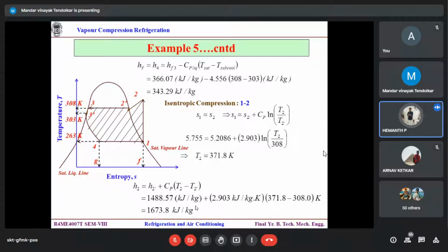Sir, while subcooling, the process will be a constant pressure process, right? Constant pressure process, yes. Because we have already stopped at 3, which is already saturated liquid, and then we are subcooling. So we will be exiting the dome, right? Yes. So I thought you have drawn it on the... Here. So we have exited the dome, right? Yes. Okay. It is slightly outside, left side.